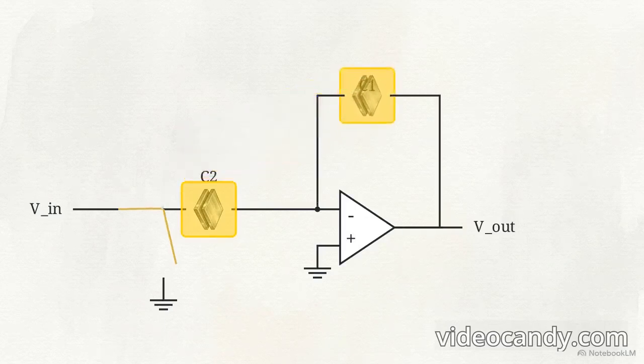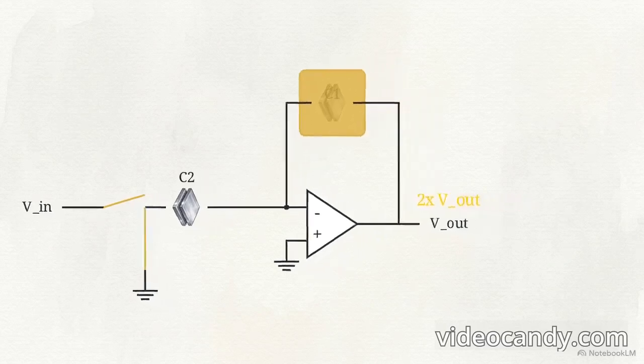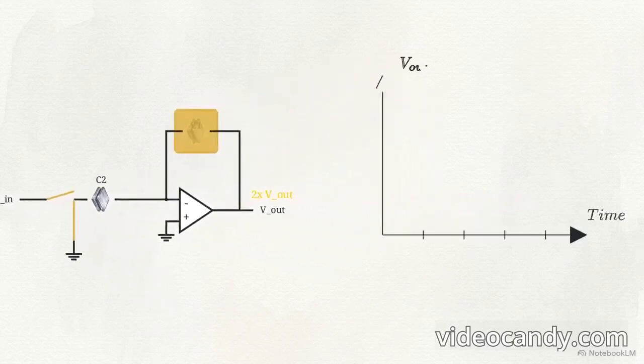This schematic shows a multiply by 2 circuit. During the initial sampling phase, both C1 and C2 are connected to the input, allowing both to track the voltage simultaneously. Then we move to the amplification phase. The left plate of C2 is suddenly switched to ground. Because the charge cannot escape the high-impedance loop, fully discharging the second capacitor forces its entire stored payload directly onto the first. We have successfully pooled both packets, doubling the charge on C1 and exactly doubling the output voltage.